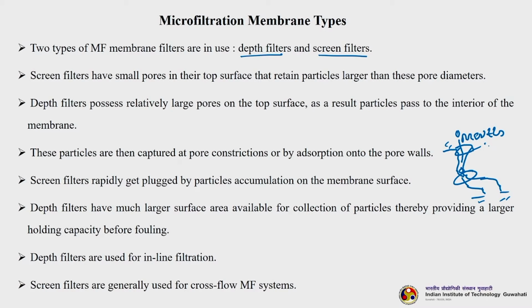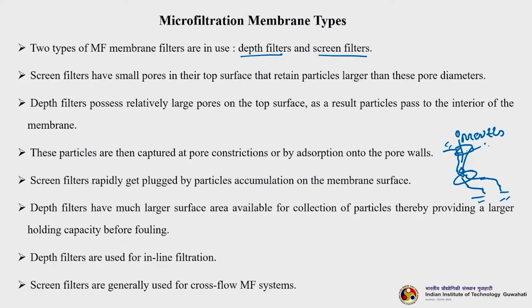It is very important to again tell you that whenever you characterize pore diameters or pore size, we are basically talking about the pore mouth, characterized from the top surface, unless you characterize the cross section. Most of the time it is surface characterization. So, the pore mouth or pore diameter is what we actually characterize, but inside there are constrictions that we do not know.